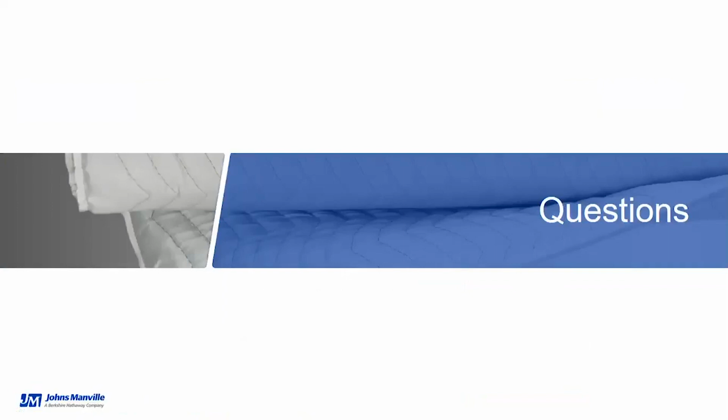Our first question is for Kelly: how does industrial hygiene sampling differ from installation in the field? Yeah, so the sampling that we did for this installation, we tried to make the conditions very standardized for each particular installation. Obviously in the field, your individual air sampling results will vary depending on environmental conditions, for example how windy it is, how big the space you're in is, and also individual work practices. So for that reason, you really do need to do your own industrial hygiene sampling in the field, especially for OSHA compliance.